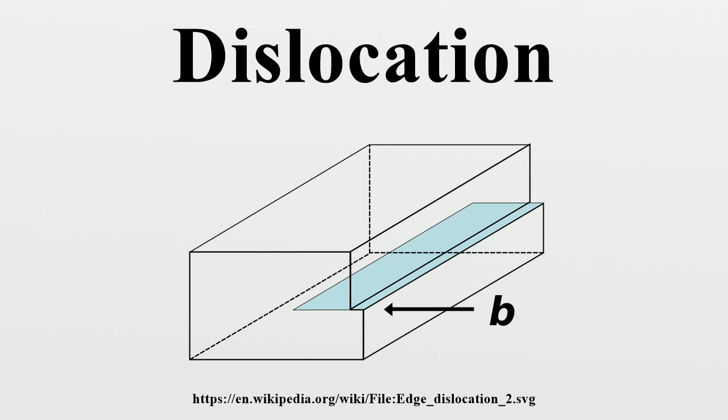as shear modulus in metals is typically within the range 20,000 to 150,000 megapascals. This is difficult to reconcile with shear stresses in the range 0.5 to 10 megapascals observed to produce plastic deformation in experiments.